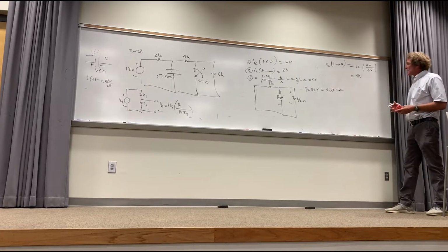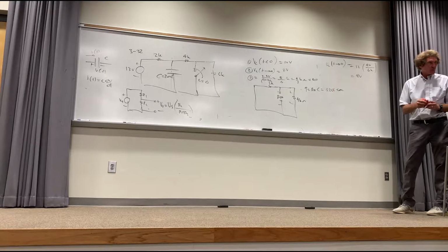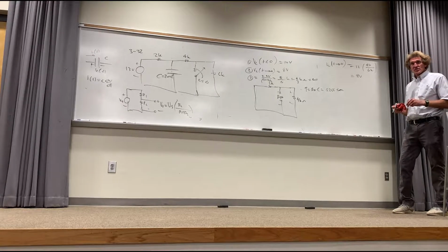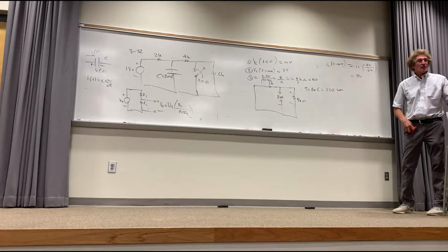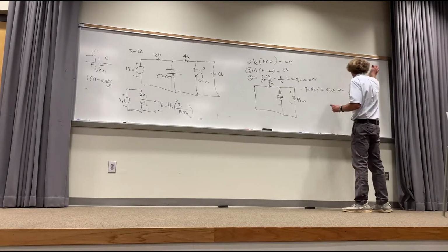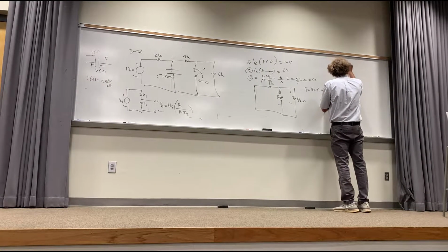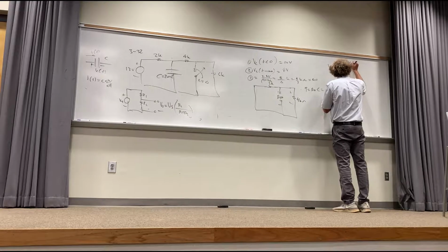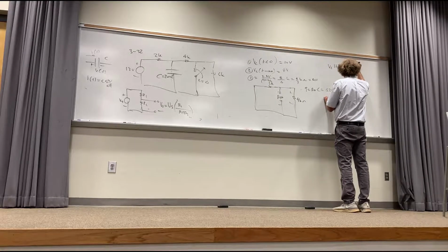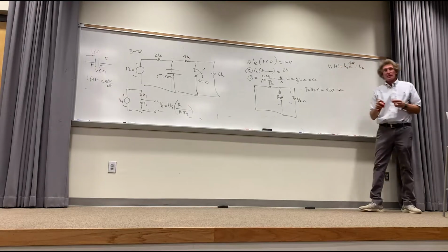Now, I get that, and now what do I do? I write the general equation, and I apply the boundary conditions, or the values for the voltage across the capacitor at t equals 0 and t equals infinity to get the constants. Correct, class? Let me write the equation. You guys will pick up on this very quickly. So now, the general equation is VC of t is equal to some K1 e to the minus t over tau. I'm just going to leave it as tau. I know it's 0.266, right? Plus K2. Right off the bat, please listen.